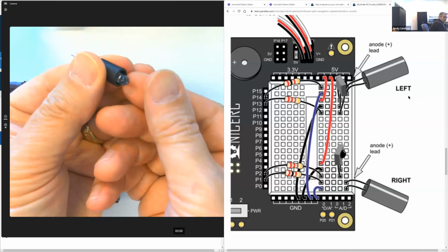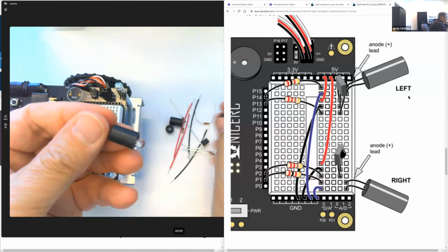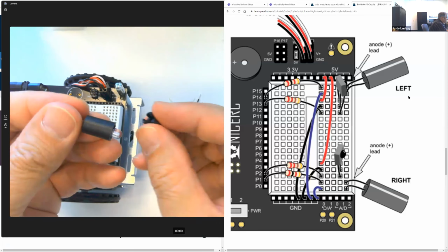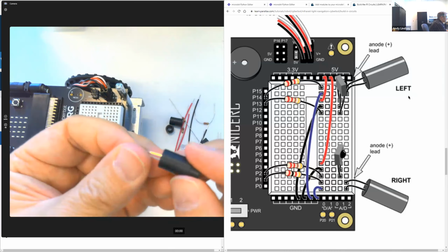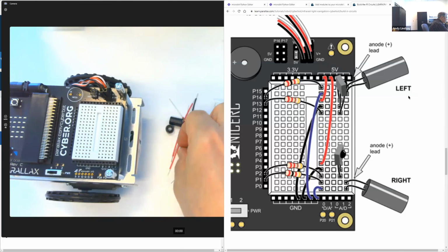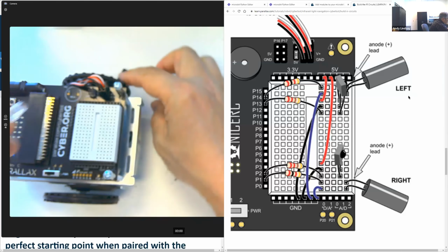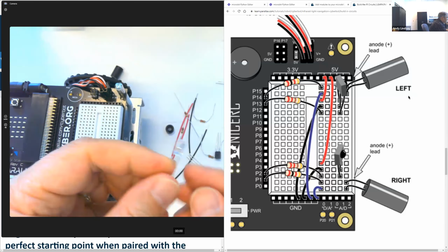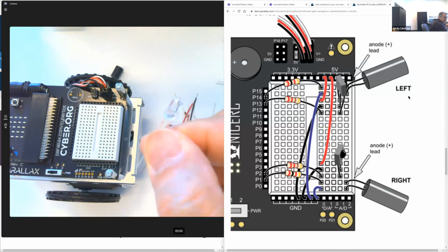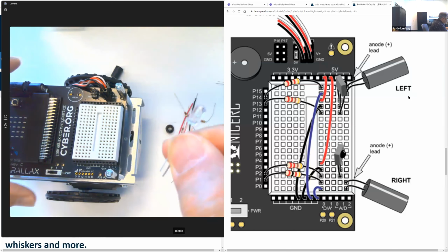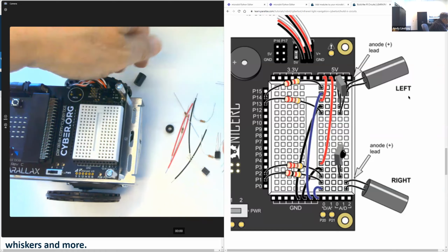And then you can push it in all the way in, and then take the little shield, the smaller black tube, and snap it on top. Do that for both infrared light emitting diodes. That's these guys with the clear plastic case and the 2 pins of slightly differing lengths.